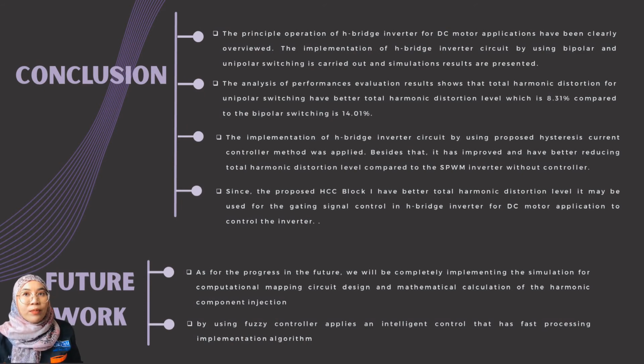The analysis of performance evaluation results shows that unipolar switching has the better THD level, which is 8.31%, compared to the bipolar switching, which is 14.01%.